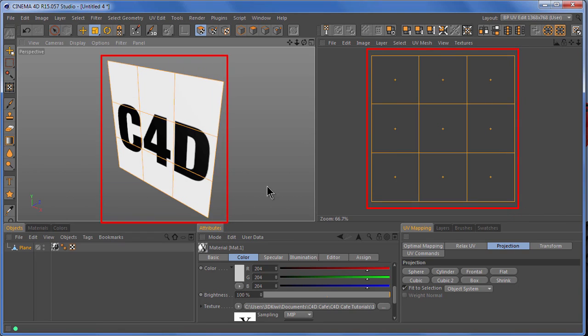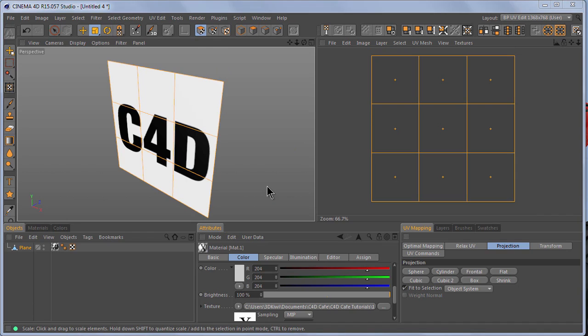Now for every regular polygon in Cinema 4D, there's a matching UVW polygon when you make the object editable. So if it's got a UVW tag, it'll have UV polygons. And in this particular case, the plane object has they're all nicely laid out because the plane object has a built-in UV map that Maxon has set up, and it's very, very nicely laid out.